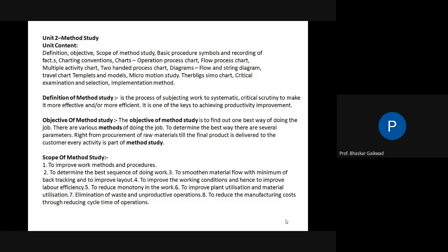This is one example. And a second example is nut and bolt manufacture. Continuously, we are manufacturing nuts and bolts. So starting from the raw material to the finished product, whatever machinery we require should be in one line. This product layout is also called line layout. So all machinery should be in one line so that once the raw material enters the first stage, it will go on processing and ultimately the final product will be there. Okay, this is the smooth movement of the raw material up to the finished product.